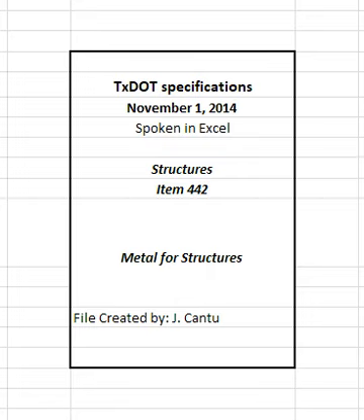3.2 Galvanizing. Galvanize fabricated steel items, steel castings, bolts, nuts, screws, washers, and other miscellaneous hardware in accordance with Item 445, galvanizing. Galvanizing is not required unless specified. 4. Measurement. This item will be measured by the pound of structural metal furnished and placed in a complete structure not including the weight of erection bolts, paint, or weld metal. This is a plan's quantity measurement item.